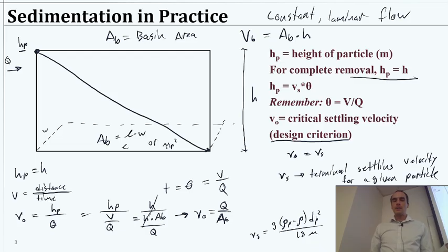And again, if you stop and think about it, if I were to pour out my liter of water on a table, and let's say it had a little track or something keeping it on the table. If it's a narrow table, it goes a little fast, right? If I give it a little pipe or something, a narrow channel, it makes its way through that pretty quickly. If it spreads out everywhere, it has more time, right, to travel that distance, whatever flow rate I was giving it. So as you expand your area for sedimentation, your water slows down.